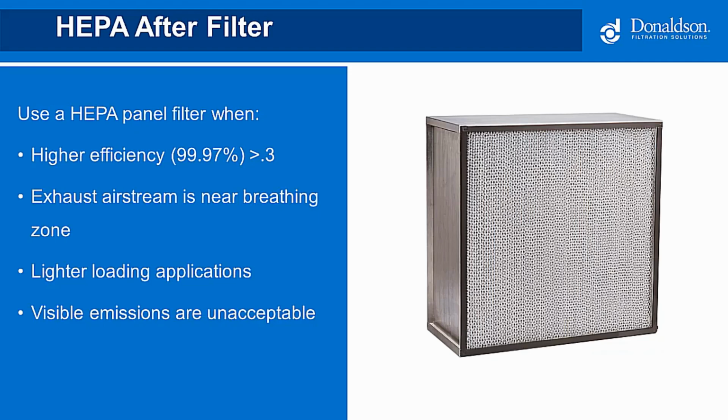We often see shops with centrifugal collectors burning through HEPAs. Also know that when they plug up, it'll back up the entire system like a clogged sink, and mist will find a way out. Just a quick note, there are dispersed oil particulate after filters, which are 95% efficient down to 0.3 microns. These last much longer for heavier mist loading applications.